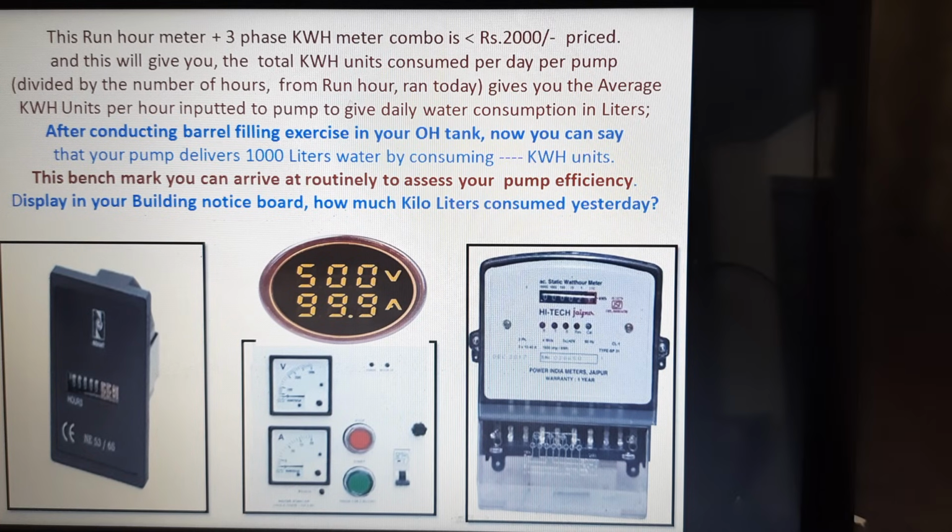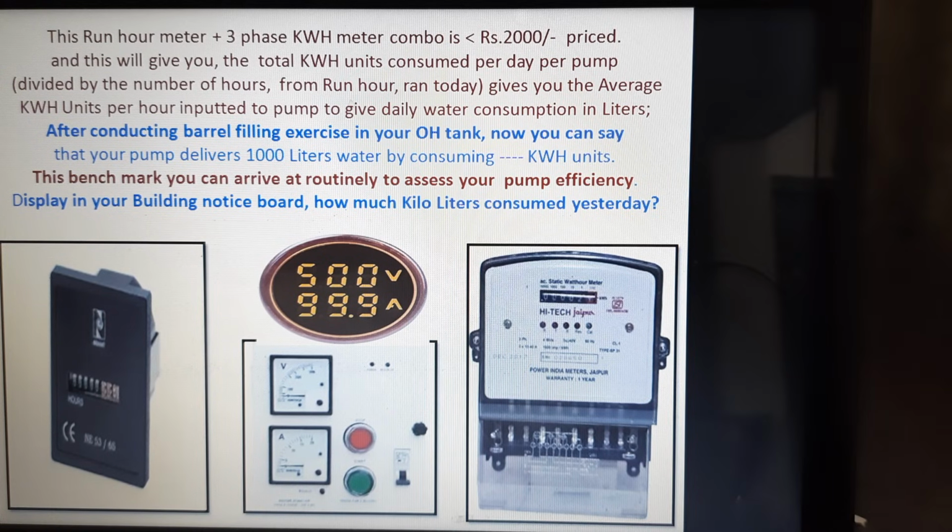And if the total units consumed are divided by the run hours for the day, it gives the average kWh units per hour input to the pump or the geyser, and for the pump it helps give the daily water consumption in liters. After conducting the barrel filling testing, we normally call this a bucket filling test,